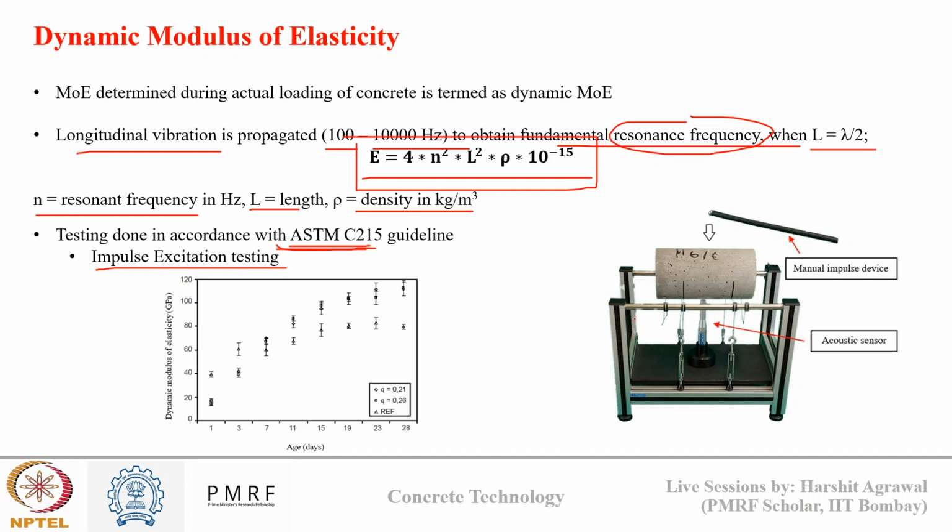Using this test, we can also evaluate the change in MOE value with increasing concrete age, as you can see in this figure. How the MOE of concrete changes with age can be evaluated easily, because this is a quick and simple test which doesn't require any extensive sample preparation or loading-unloading profile. So for such cases, this test is preferred. For practical applications in real-world conditions, like bridges, pavements, and high performance concrete, dynamic modulus of elasticity is a convenient way to move ahead.